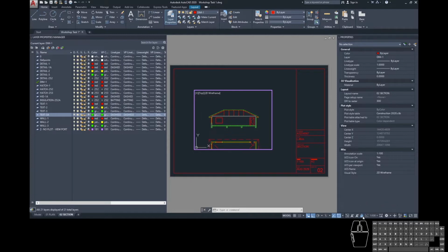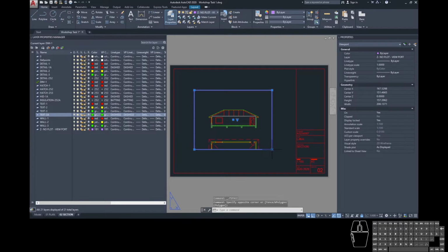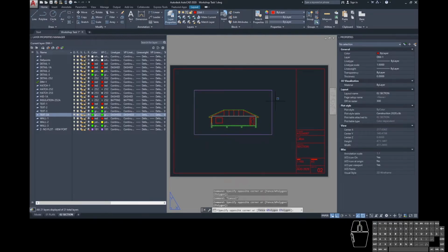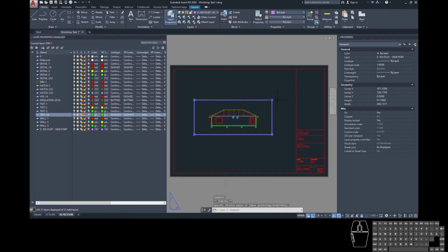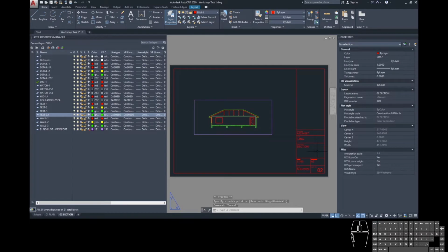We can then click the lock again, and then deactivate the viewport by double clicking, and then of course also bring that up to reframe the viewport how we want that to sit. So they're two very similar ways. It's just that the first way has slightly less risk of accidentally moving your drawing out of scale.